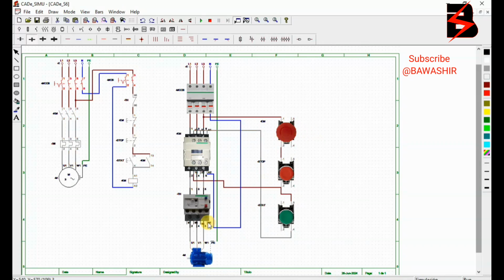So that means we had used a faulty overload. So engineers, please, you have to put that into consideration, testing of the equipment that you're using. But since this is software, they have bugs and errors and whatsoever, but the basic concept would be first passing through the 95 and the 96 of the overload, whether through the neutral or through the live, it will break the circuit. It does not matter. So start, our motor runs as you see.